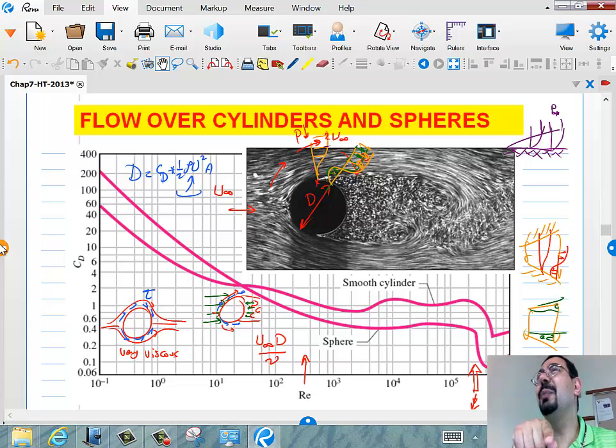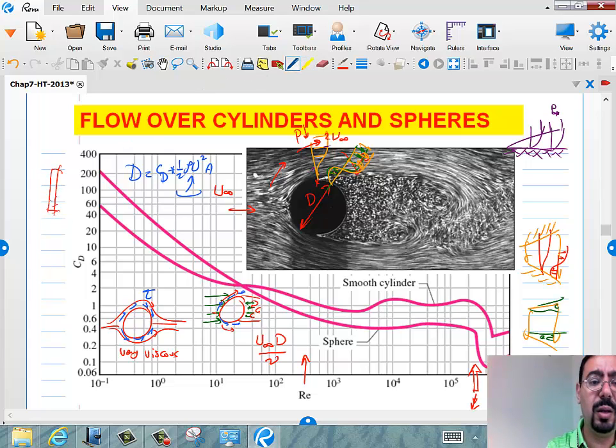Next section in the chapter is flow around spheres and cylinders. So what you're looking at is basically the wake behind the flow. So the flow comes like this, and then what makes it separate? You could think about this just like, if the flow is over a bluff disk like this, the flow will have to separate here, right? Because the flow here cannot just turn 90 degrees.